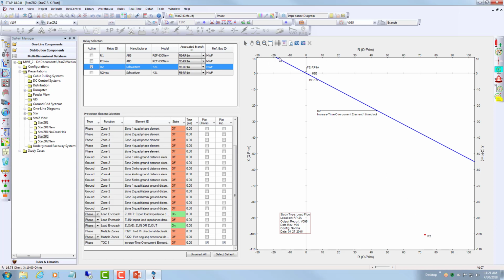in the case of the SEL relay, the directional overcurrent protection does not have that many settings. It's just the line angle that we set, which is 62 in this case, and the forward and reverse angles are basically minus 90 to plus 90. So we are covering a wide range, and that actually increases the chance of false tripping.